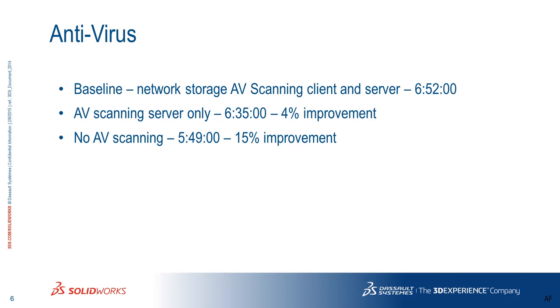Then we turned off the scanning for the client, and we only got a little bit of benefit. But when we turned off the antivirus scanning for both the client and the server, now we've got a noticeable difference. 15% is nothing to sneeze at. If you guys could get 15% more out of your day, you'd be happy about that, right? So there's a lot to be said for making exceptions in your antivirus software to exclude SOLIDWORKS files.